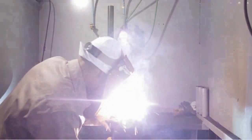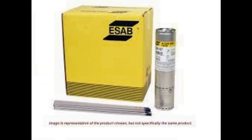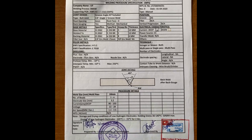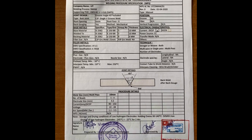On the basis of past experience from various sources like the company's welding personnel, including the welders, and information from resources like the welding consumable supplier, draft a weld procedure on the WPS form.